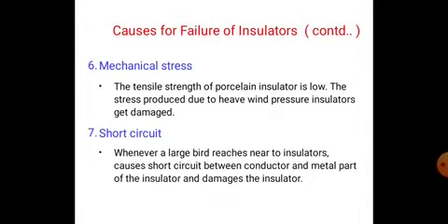Short circuit. Whenever a large bird reaches near the insulators, it causes a short circuit between the conductors and the metal part of the insulator and damages the insulator. Due to these large birds, the insulators get damaged.